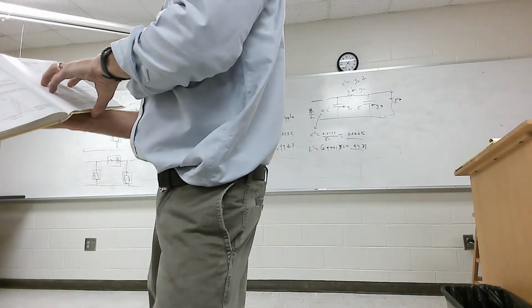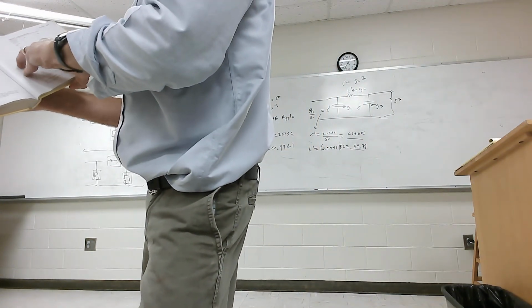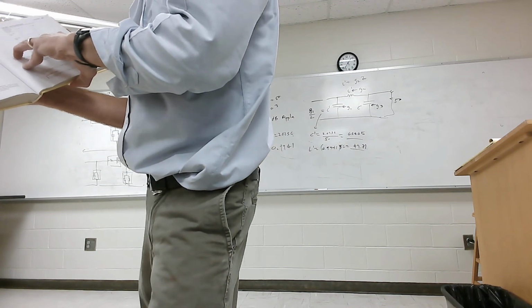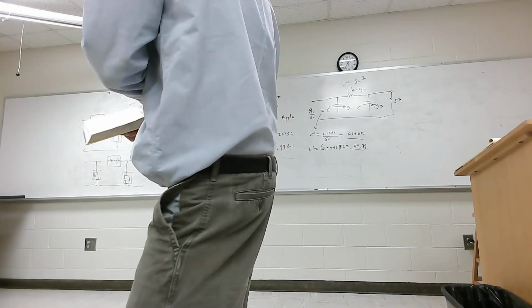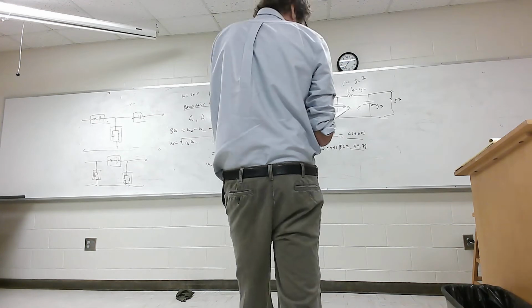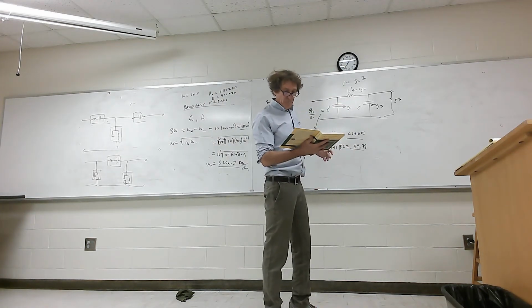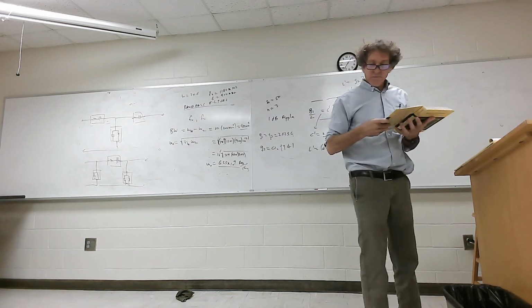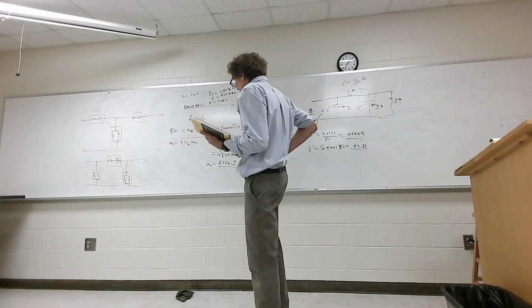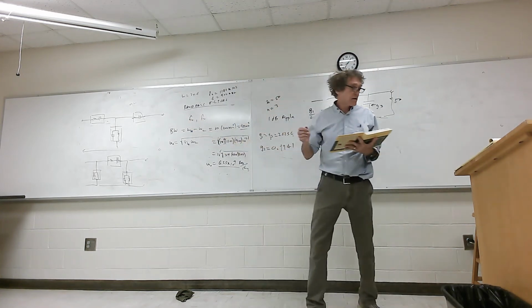But if you look there, you're going to see anytime we have series elements, we get the L prime, and that would be here. That's L prime. And we divide by the bandwidth to get the actual value of L. So, let me do it this way.